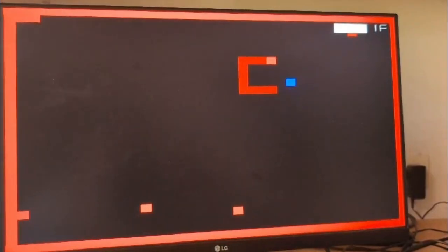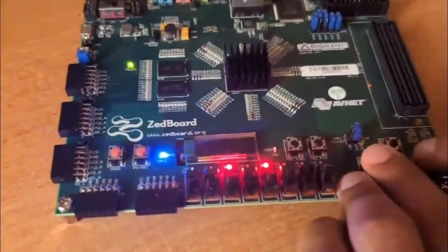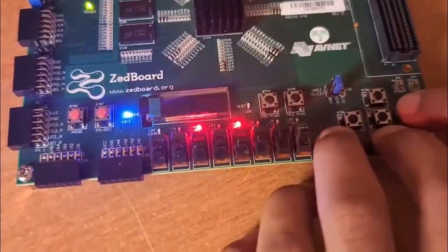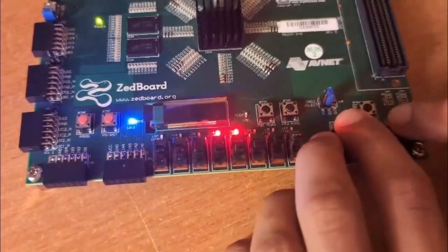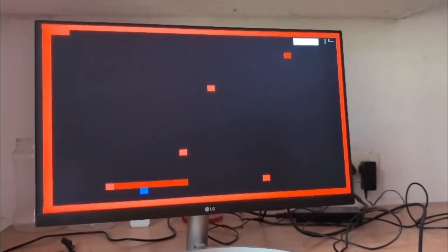Now we can see the score after eating an apple is increased to 18 on the top right corner, and correspondingly it is also increased on the ZED board LEDs. The score array is a 7-bit array, so we can see the corresponding binary digits and convert it to decimal to see the score. To get eliminated in this game, a player has 3 choices.